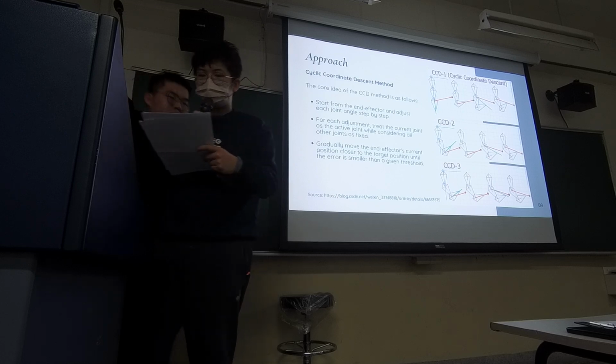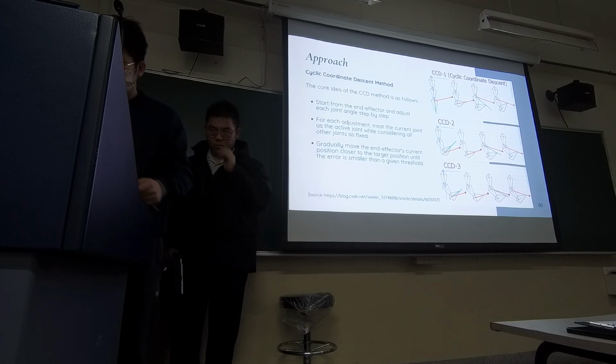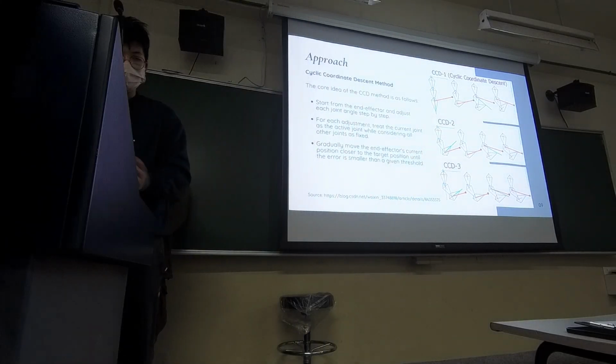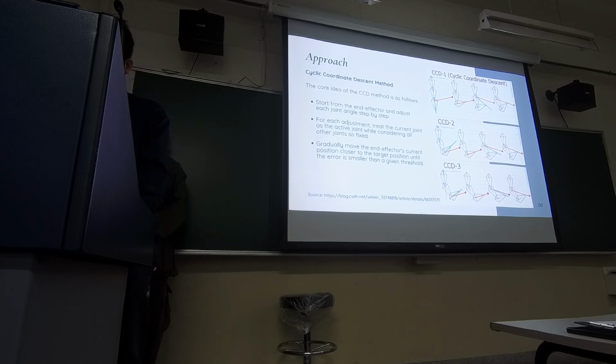Earlier we mentioned that since we have 5 joints, which means 5 variables, but only 4 equations, x, y, z, and gamma, this leads to infinitely many solutions. To address this problem, we use the cyclic coordinate descent method to compute the appropriate joint angle and the translation distance.